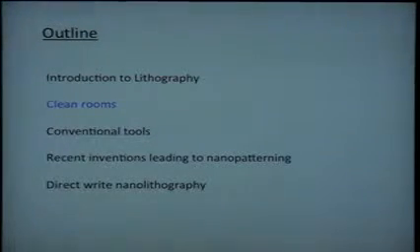So if I draw a 10 nanometer line, it is as good as bringing in a big stone and keeping it next to it, or dumping something on top of it. So the pattern I'm writing will not serve me eventually in a given device, because its properties will be altered by the dust itself, right? So you need to have control on the dust in the environment where you are creating the patterns. And that's why you cannot be doing it in the ambient like this. You can hardly do patterning in the ambient.